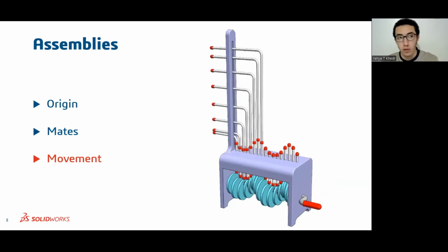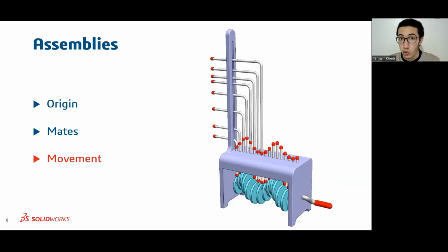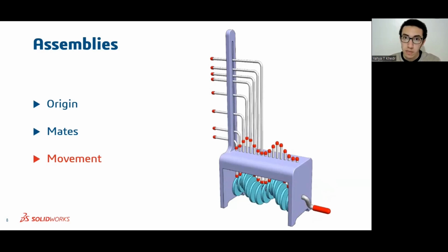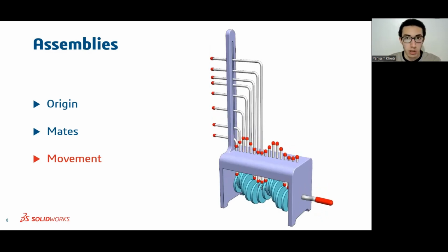If not, for example, if a certain component is fixed, or moves irregularly, or is flipped, that will mostly be obvious to you if you're trying to move the assembly around rather than just looking at it from different angles. So that's a nice tip for you guys. It's obviously helped me a lot before, so I'm certain it's going to help you as well.